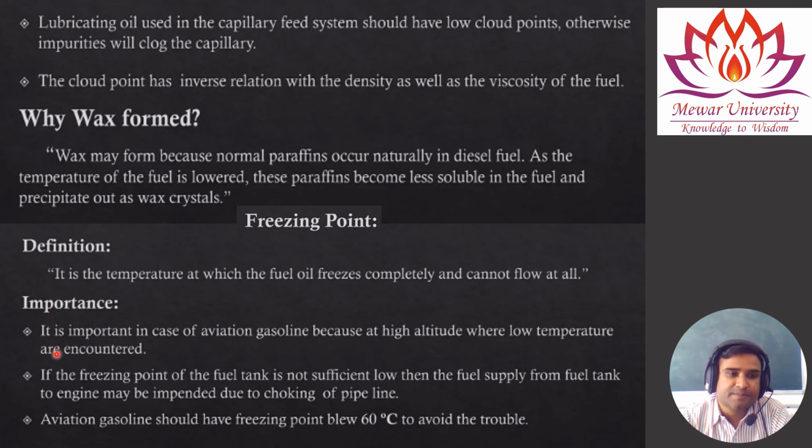So why is it important? It is important in the case of aviation gasoline, because at high altitude, low temperatures are encountered in the planes, and in that case the fuel will freeze. Once the fuel is frozen, it will not flow into the engines.